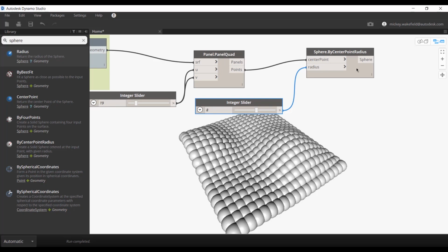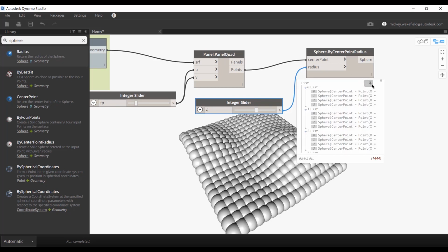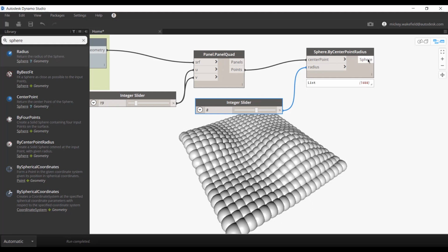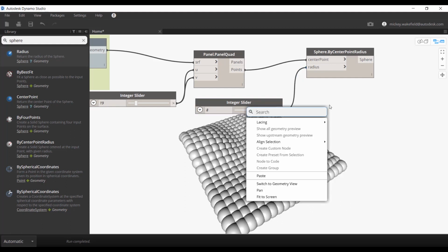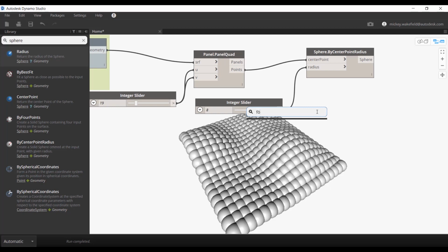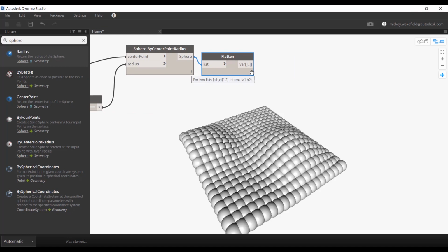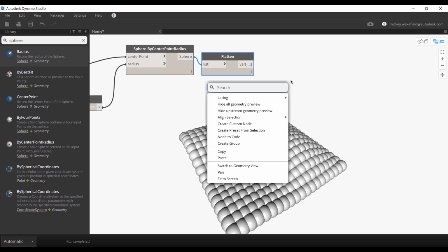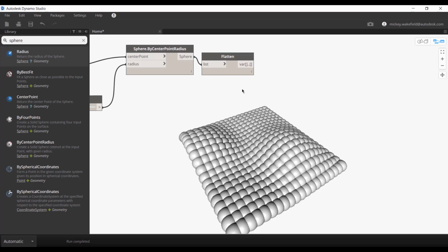It's just an idea. In any case, the next thing you're going to do is export all those, but you can see that the spheres are all in sublists because it basically splits the spheres up into each sphere being on one of the UV lines. So before I export this, I'm going to flatten that list. Instead of having a list with a bunch of sublists, I'm going to make one giant list out of it, all of them in one. That's a command called flatten. And that makes that list into one giant list without UV line 1 and then all the spheres on it, UV line 2 with all the spheres on that line.